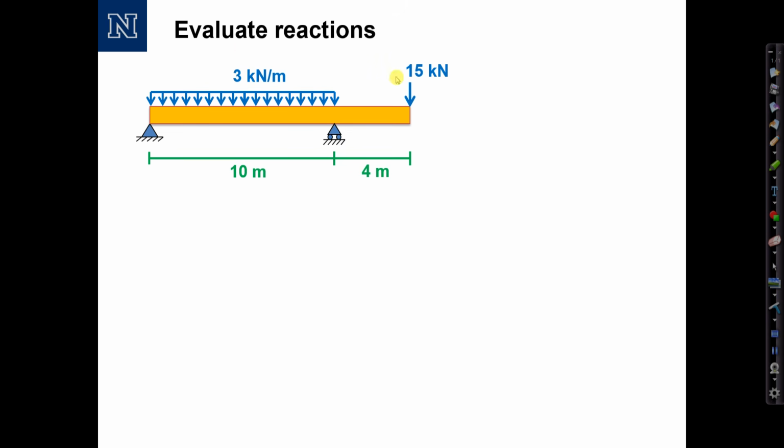This is a beam, a simply supported beam with an overhang. Notice that it has a pin support at the left end and a roller support in the middle, for a total of 3 unknown reactions. We have 3 equations, so this is statically determinate. Knowing that, I would draw a free body diagram of the system, and I would start out by representing the beam as just a straight line.